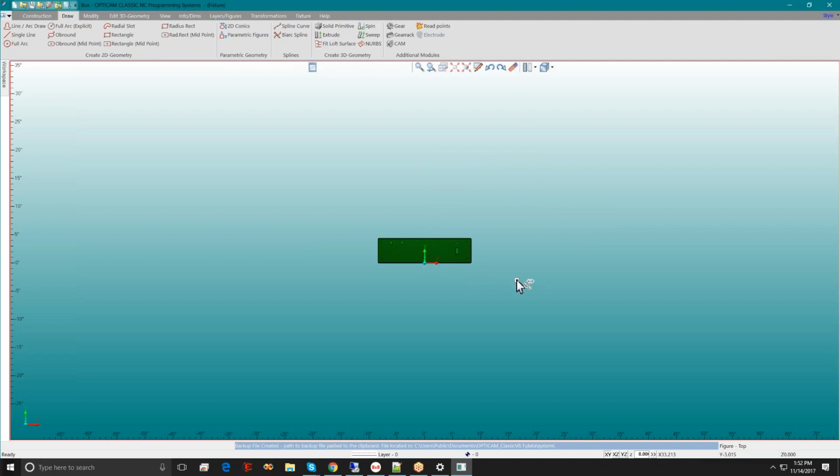For instance, if I wanted to make a special shape to constrain the height of the fixture, I could do that by drawing a boundary and making a user-defined shape. If I had a very formed part where I wanted to maintain a nice fluid top surface, I could draw a sheet, a rough sketch over the top of it, as if you were sticking a blanket over the top of a part, a blanket that fits the form of the top of the fixture.